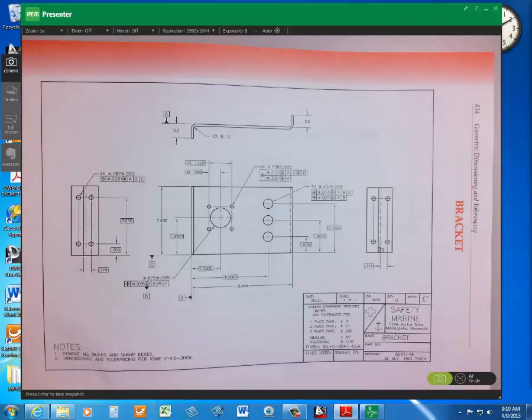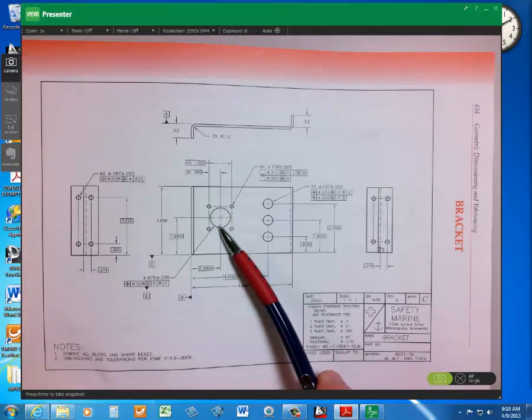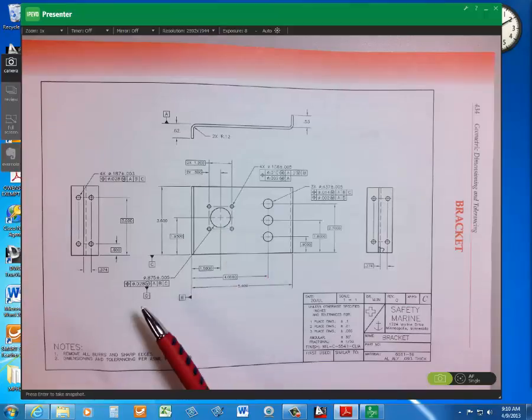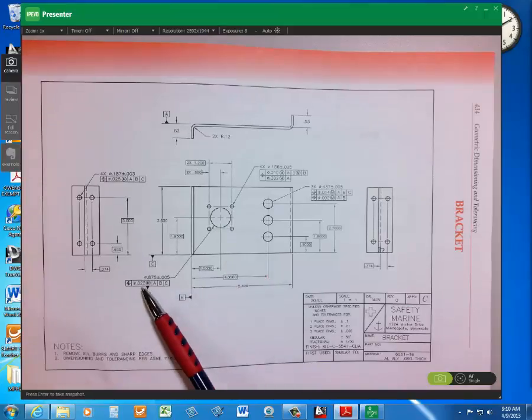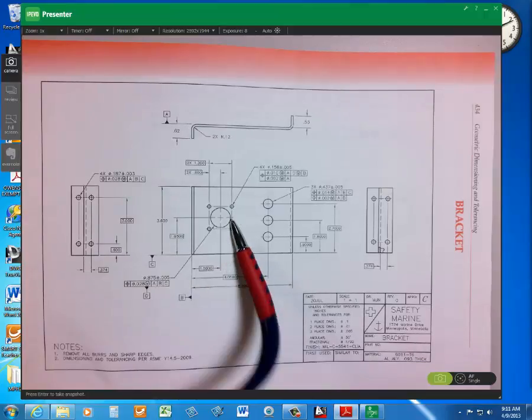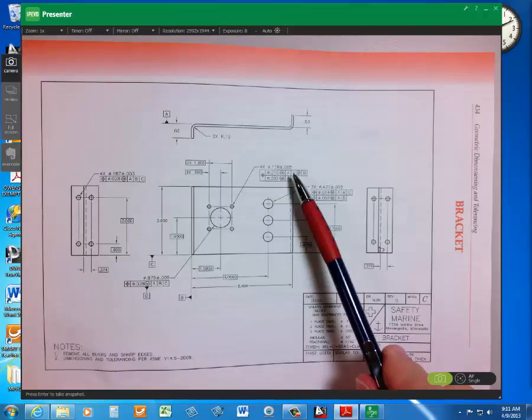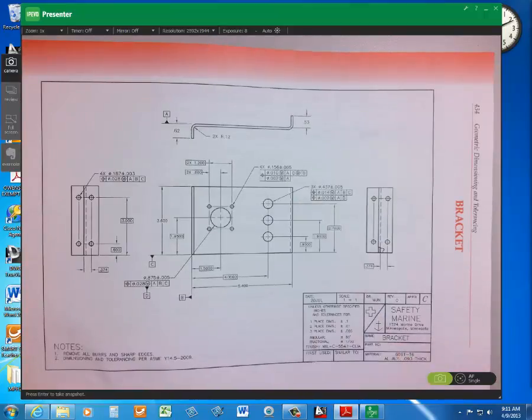So when that large hole is datum, the axis of it is datum D. So when it is 14 thousandths of an inch over to the right, let's say it's been produced and it's over to the right, then this pattern as a group of holes can be over 14 thousandths as a group.